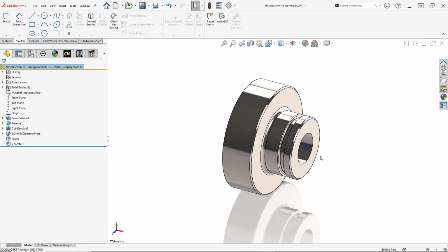One feature required to properly establish the CAM environment is the use of a fixture coordinate system, as this defines the home point or main zero position of the machining center. This assignment is mandatory, as it properly orientates the defined machining center on how it approaches and machines the part.